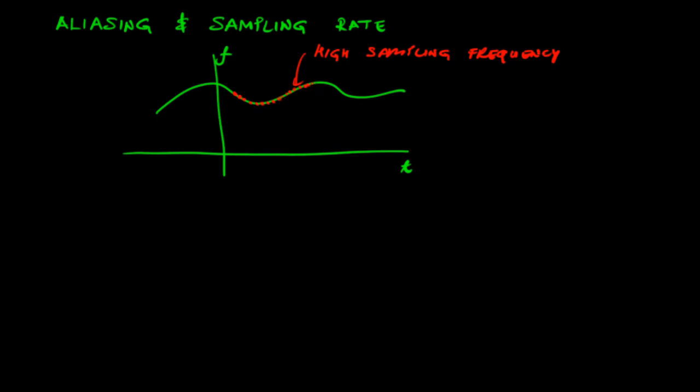However, sampling at a high rate would mean that we need an expensive data acquisition system and also higher memory requirements. For example, if you are capturing images of certain physical phenomena at very high frequency, you'll soon see that with a very high frame rate you'll have gigabytes of data, although in certain cases that might not be required where the physical phenomenon evolves slowly in time.